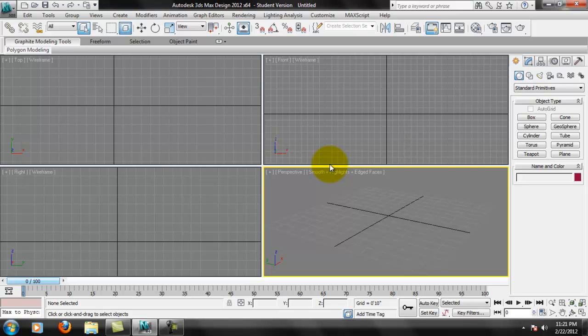Usually what I like to do, or what ends up happening, is I'll complete my Revit model with my sheets and everything, and I'll import the 3D Revit model. And when I import that, the units will come in. Basically that does two things. It gets a lot of work out of the way for you, for one. And for two, it gives you a sense of scale. So working from the size of your rooms, or the thickness of your walls, you can get your object close enough to where it looks right in a rendering.